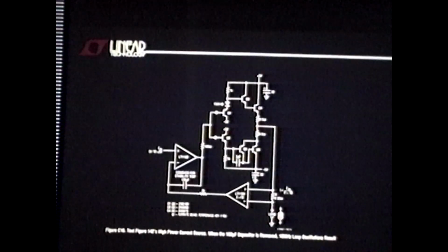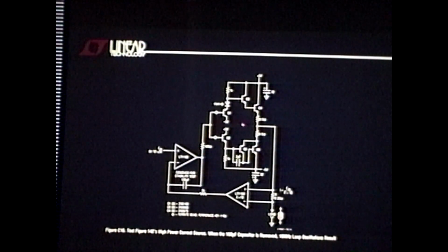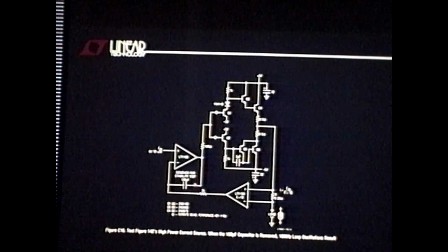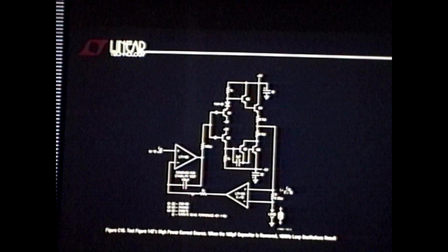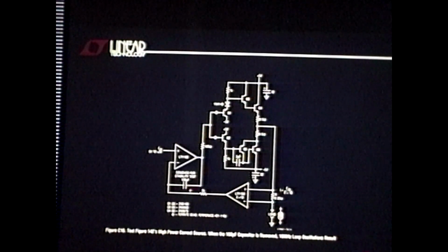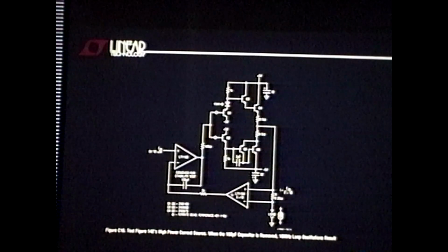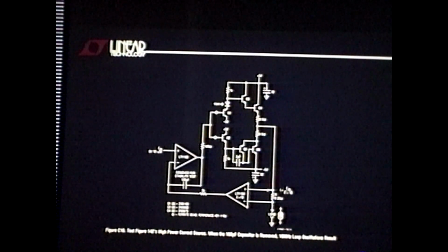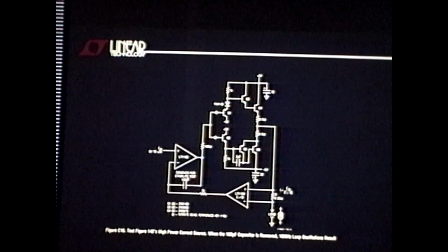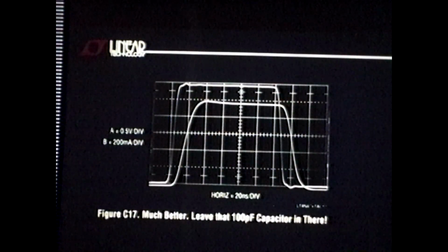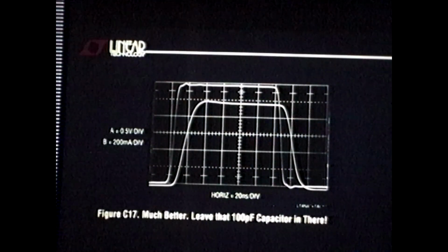We missed it. There's a picture missing here. This thing screams like a banshee with this capacitor out here. We're missing the picture. If it screamed with the cap out here with just this delay, it's certainly going to get into trouble with both of these things in the loop, unless we kill the gain bandwidth locally. With the cap in, it's happy. The picture you want to see, I ain't got.